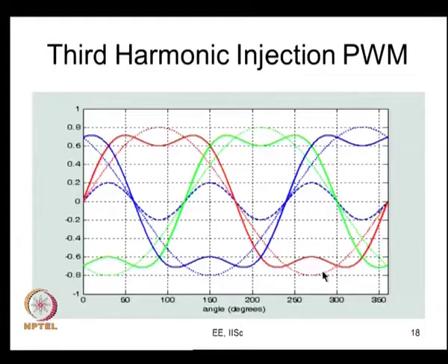It is the same nature of curve. Here 0 becomes 0.5, that is essentially the difference, and this is 0, 0.5 and 1. You just change the scale and draw, and now this M R star will give you the duty ratio. So, you can calculate the duty ratio. Once you calculate the duty ratio, it is possible for you to calculate the conduction losses. Once again, as I said before, you can calculate the conduction loss as a function of modulation index and your current amplitude and power factor angle.